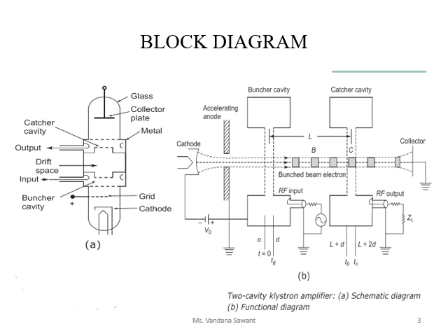the electron will get decelerated, or the bunch of electrons will get decelerated, and they leave their energy to the field. Their velocity gets reduced, and they give out their kinetic energy. And that kinetic energy which is released by the electrons will be caught by the RF field which is present inside this catcher cavity.